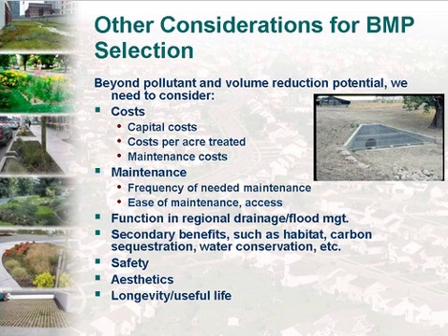The next bullet is function in the regional drainage and floodplain management program, and that's extremely important. We have to remember that although in many cases our focus is on enhancing water quality, the features that we're talking about fit into a broader drainage system. It's incumbent upon all of us to plan, design, construct, and maintain urban stormwater management systems that not only protect receiving water quality, but that protect the public from dangerous flooding. We have to provide assured flow paths for up to, if not over, the 100-year flood without homes being damaged, and the role that BMPs play in that sense is very important.